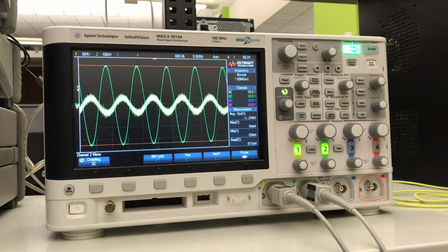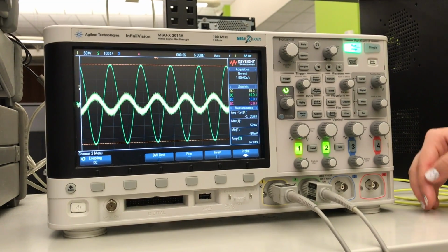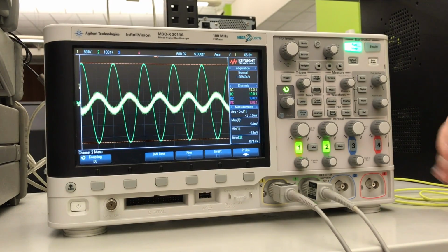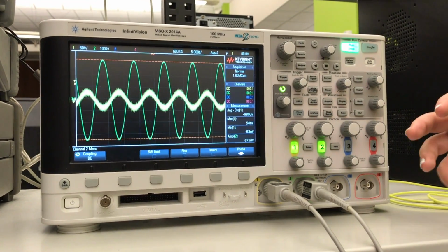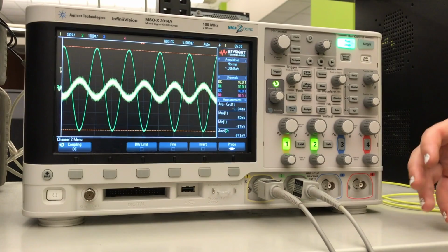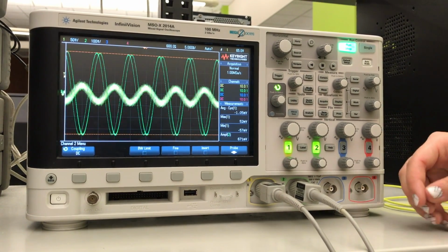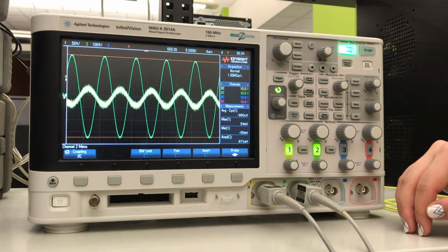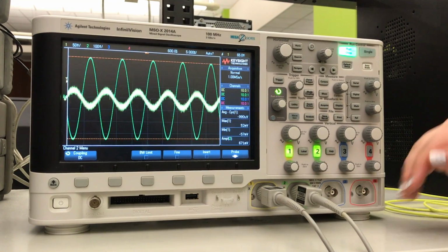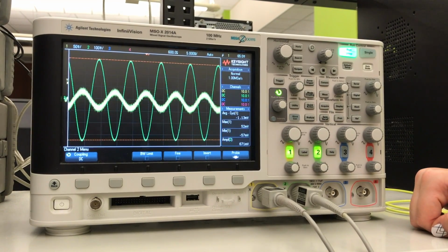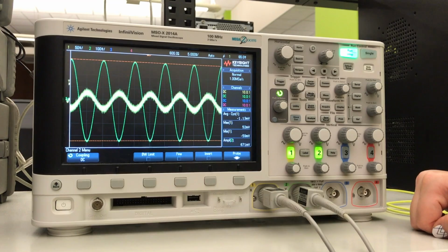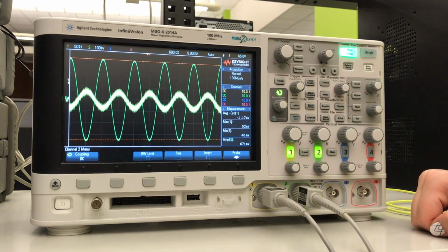You can think about these signals as being infinite in time. It's a sinusoid, but it continues indefinitely. In order for the oscilloscope to display something that's easy for us to understand, it wants to pick a constant point to show in the same spot, so the signal doesn't move all over the place. It can be really useful to change how you're triggering in order to make the signal sit still.